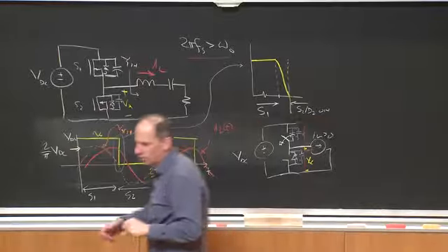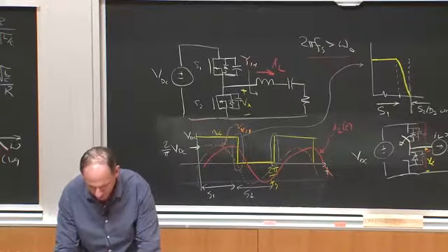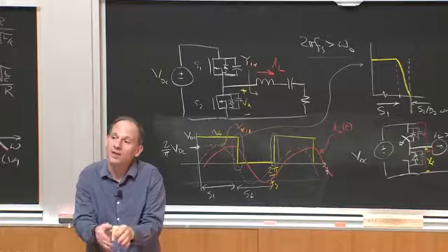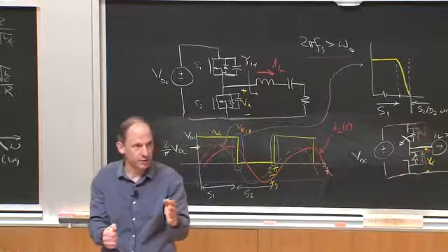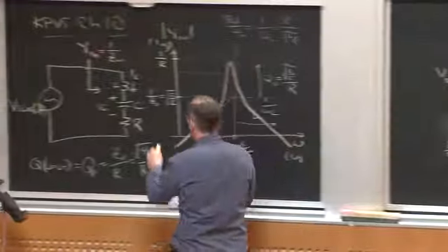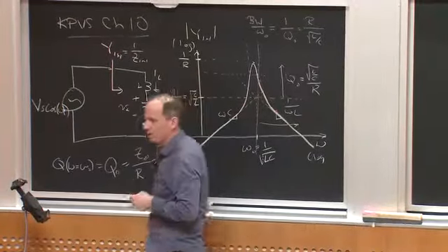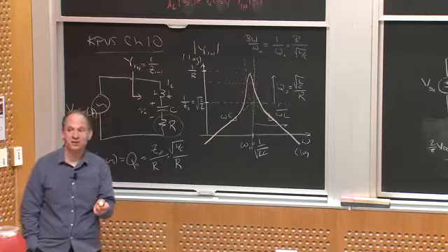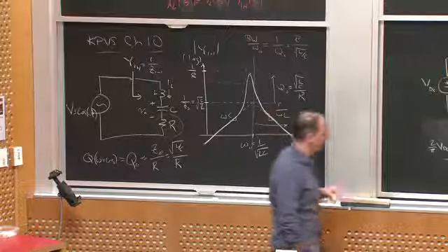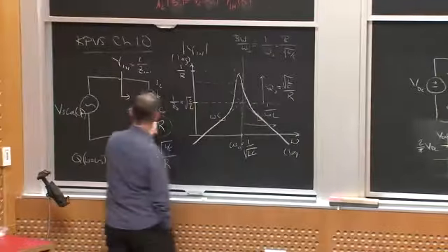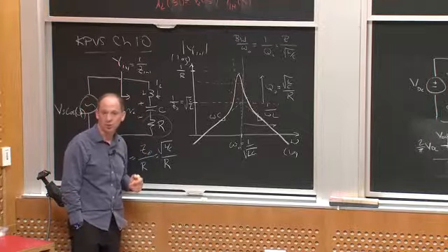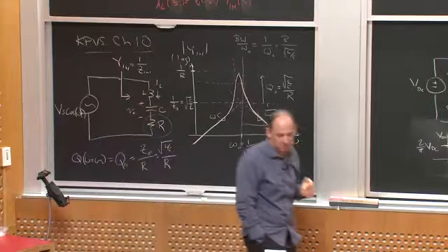All right, so we can get 0 voltage switching. And by doing that, we can go at pretty high frequencies. And then we can use frequency modulation, frequency control, to control the power into our load. Now, what is our load? Well, I haven't said what this load is. This load could be any number of things. It could be, for example, the equivalent resistance of an induction heating load. And thereby, by modulating frequency, I modulate power, and that's how an induction heater can work. And I can run at high frequencies because of that.